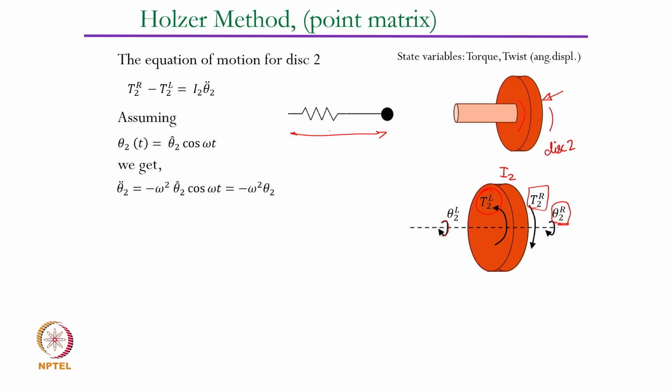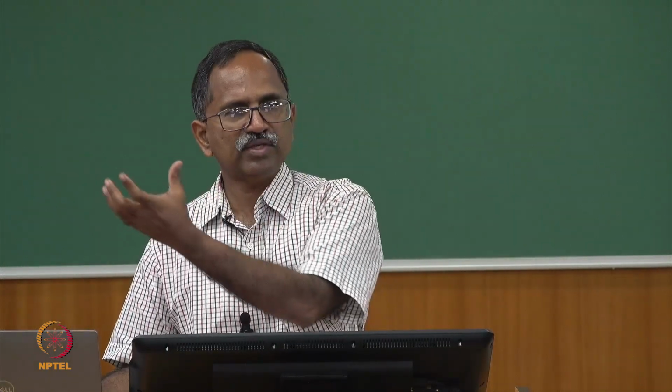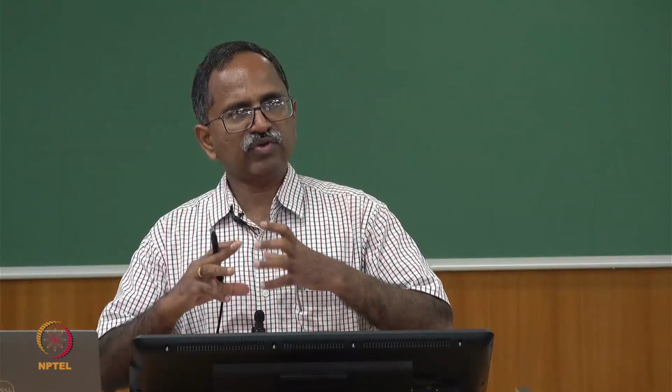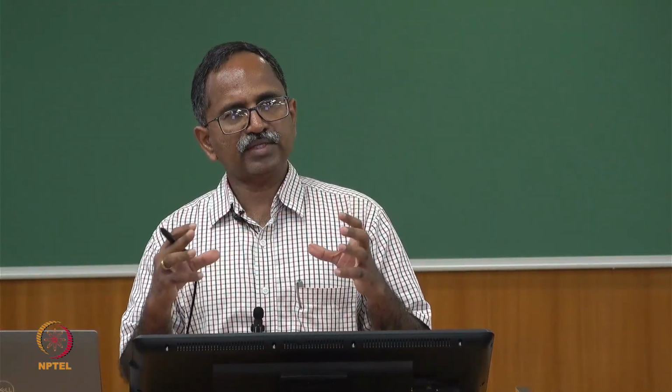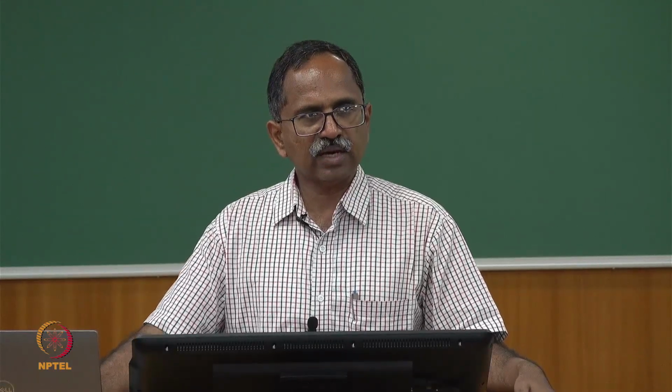At any of the eigenvalues, the entire system, be it segment 1, segment 2, segment 3, segment n, all these segments are going to exhibit a principal mode or normal mode of vibration, wherein all the elements are going to oscillate at the same natural frequency. It is not going to be like segment 1 vibrates with the first natural frequency, segment n vibrates with the 10th natural frequency. It does not happen like that, right.